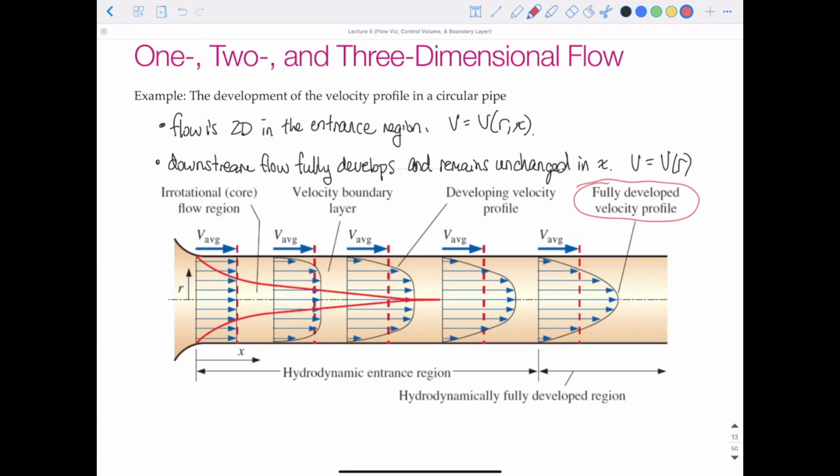So a lot of times when we do our analysis of fluid flow, we have to assume for our one-dimensional equations that we have fully developed flow. So we are doing our analysis at a section of pipe that is beyond any geometric change that is going to require a boundary layer forming, such as an entrance or maybe a device in the way that's disturbing the flow. So fully developed flow, we say this just means that we have one-dimensional flow in a pipe, and it's not changing the flow at one section of the pipe as long as the diameter stays the same.